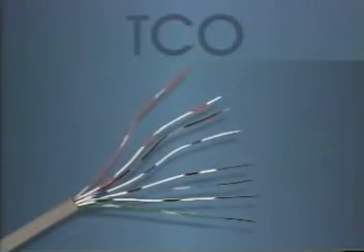Looking at the types of cable we would see cable such as copper cable. Plain old pieces of copper wire which have been wrapped in protective devices, sometimes plastic, sometimes metal, sometimes combinations of plastic and metal. Cable that's going to be buried in the ground is going to be designed and built differently than cables that's going to be hanging from a telephone pole. Very often the cable that's hanging from the telephone pole sags and is subject to ice and snow and strong winds, so it's built with a supporting steel strand built right into its protective covering to give it that added strength. Of course, cable buried in the ground doesn't have that problem, so you wouldn't find it with that cabling.